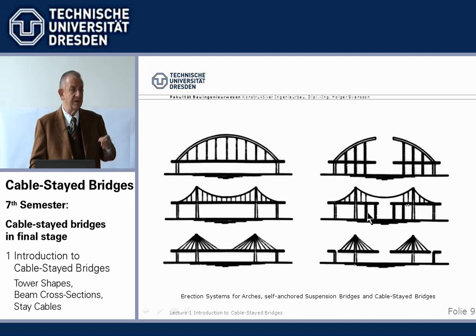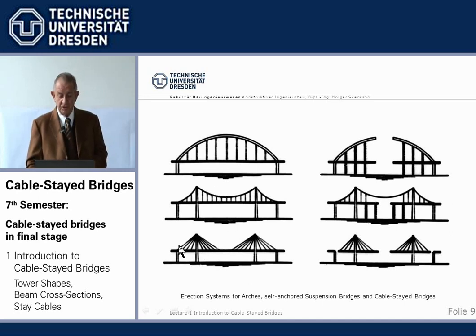has to be temporarily supported by auxiliary piers. Completely different flow of forces during construction and in the final stage. Differently for cable-stayed bridges. Now, cable-stayed bridges carry their loads in the cables back here in compression in the beam. And when we have initial systems, we free cantilever them to left and right, and we have the same flow of forces in these construction systems.